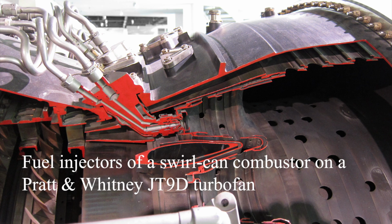The vaporizing fuel injector, the third type, is similar to the air blast injector in that primary air is mixed with the fuel as it is injected into the combustion zone. However, the fuel-air mixture travels through a tube within the combustion zone. Heat from the combustion zone is transferred to the fuel-air mixture, vaporizing some of the fuel before it is combusted. This method allows the fuel to be combusted with less thermal radiation, which helps protect the liner.